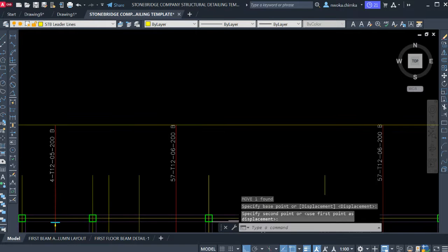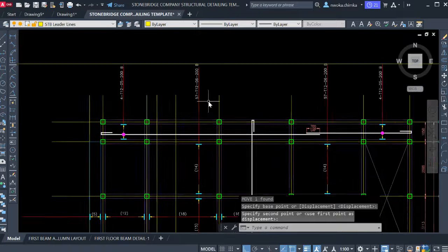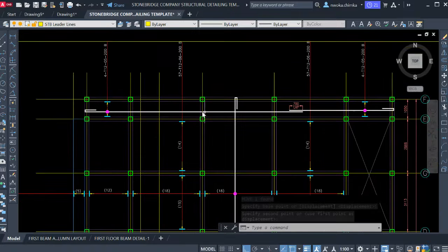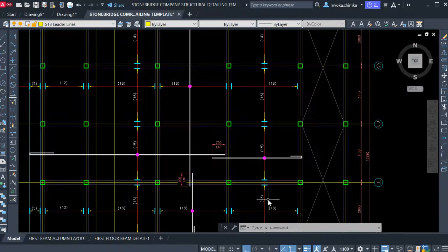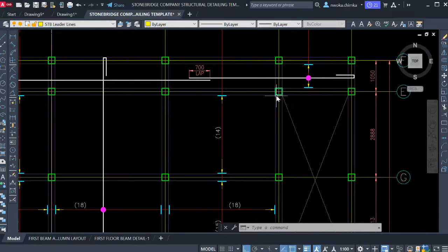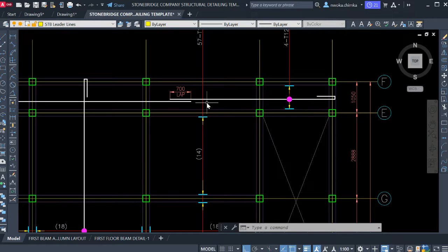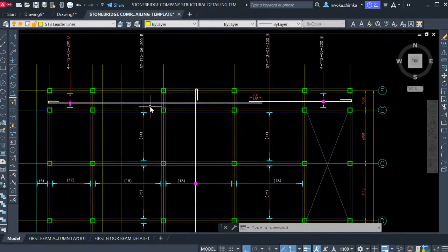Okay, you can see what you have gotten right now. So again, right now we go again. You have gotten this bottom and this bottom, and so this bottom bar runs from this point to this point, stops because the shape has changed. Now this one picks it up from where this reinforcement stops and continues to the end. The same thing happens here.